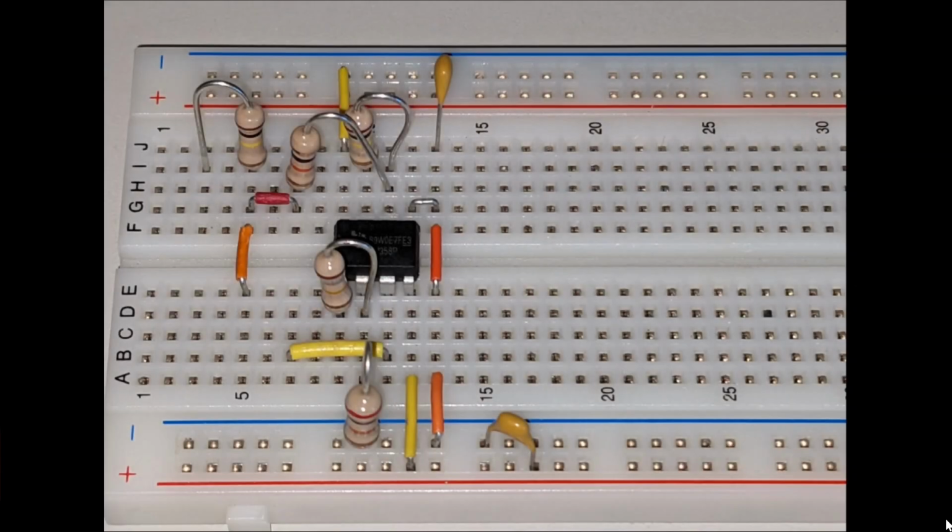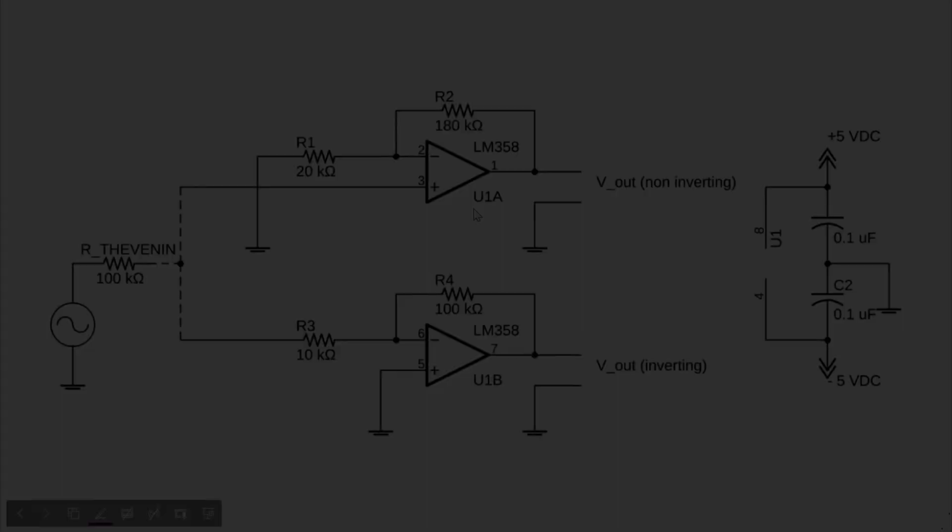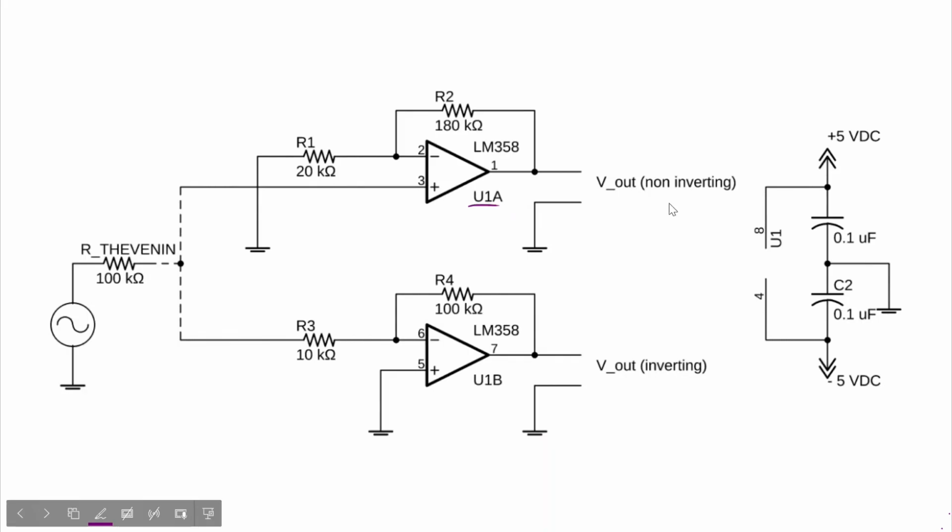It consists of an LM358 op-amp with the lower section, which is to say the A section, set for non-inverting with a gain of 10, and the upper section set for inverting, again with a gain of 10. Part A of the LM358 is used as non-inverting, Part B as inverting. Let's not forget the power supply connections on pin 8 for 5 volts and pin 4 for -5.